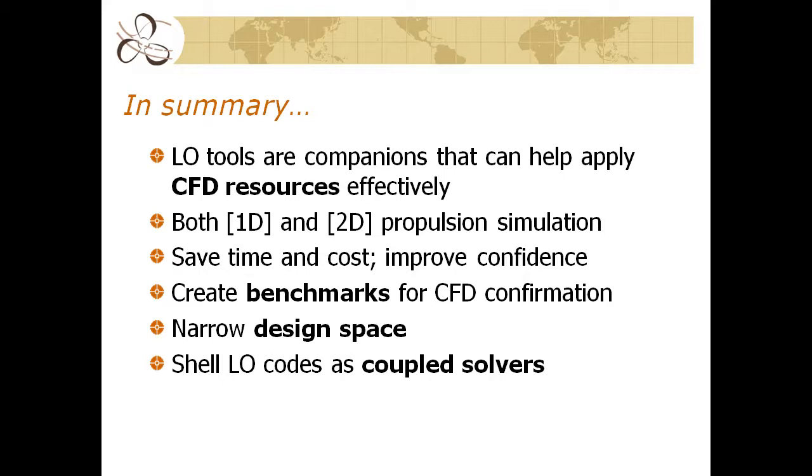And we can find ways to use CFD more effectively by reusing analysis results, or even finding ways to start CFD closer to the final answer to improve convergence. But this idea of confidence really is the underlying theme of all of this. The end of the game is we need to have a confident prediction, and we're going to use all the tools that are available to us, from simple charts to higher order codes to model testing to sea trials. And the lower order codes are an absolutely important piece to that puzzle leading up to successful use of CFD.